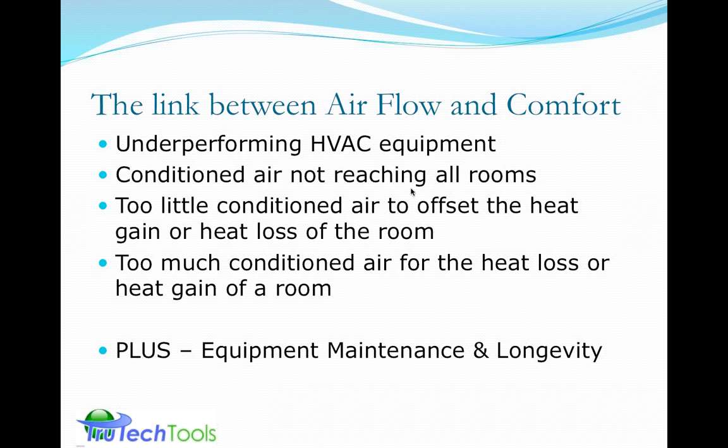There's also the correct delivery of air, that conditioned air reaching all the rooms in the living space or the working space. Also not having enough conditioned air to offset the heat gain or heat loss of a room, either due to infiltration, exfiltration of air from the surrounding, or perhaps solar radiation or cooling, or air washing, things like that. And there can also be too much conditioned air for the heat loss or heat gain. So too much can cause discomfort issues. Too little can cause discomfort issues.